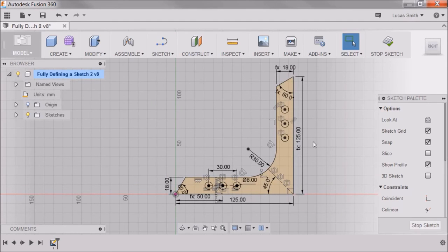The 2 outer edges increase in length, and the position of the circles remains at 40% of the bottom edge. At the same time, the entire sketch remained fully defined and maintains its symmetry on the other side of the construction line. Fully defining sketches in terms of the model's design intent is extremely powerful and allows you to update the model with simple changes. This will create a robust model that can be easily adjusted at any time.